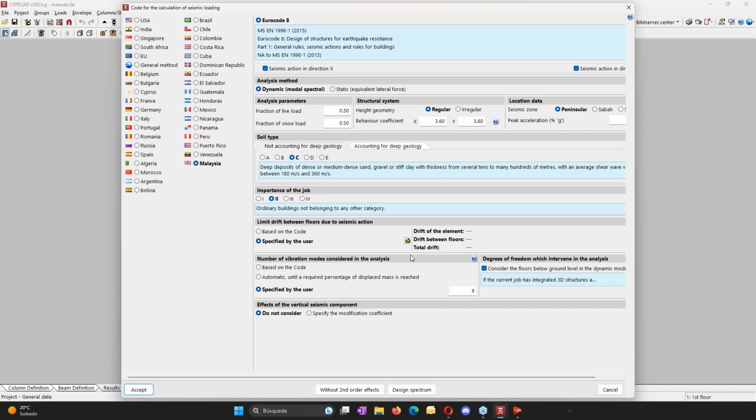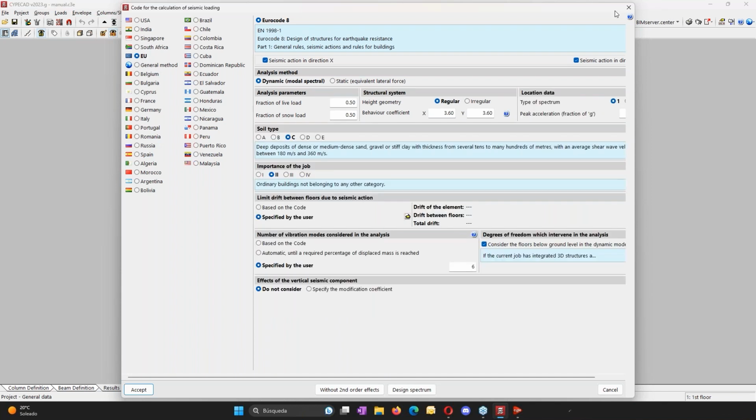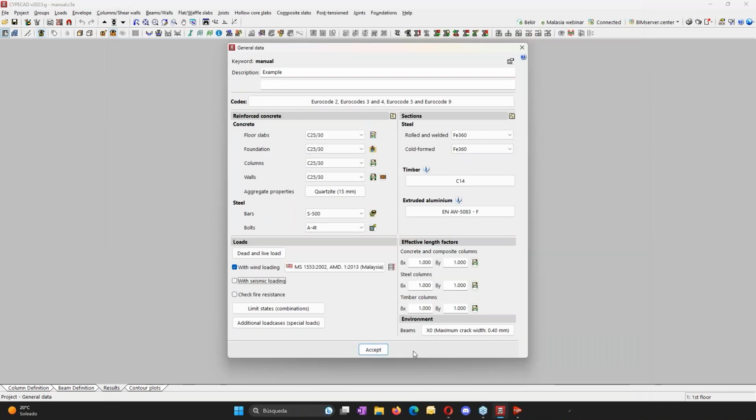But of course, if you are going to use the European Union code, you can write it. So for CYPE 3D, for the wind loading, you can use the European Union codes, and you have to fill those parameters manually, because the implementation of the wind loading in the project on CYPE 3D is very important, and it's a very big part.